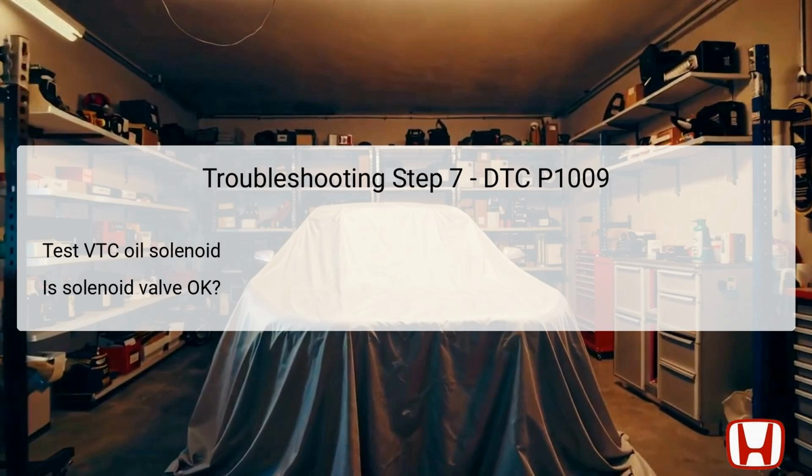Documenting the results of this test is crucial as it directs the next steps in the troubleshooting protocol and ensures that subsequent components are not unnecessarily replaced. Following the verification of the VTC oil control solenoid valve, the next step involves inspecting the VTC actuator itself. The actuator is responsible for receiving oil pressure from the solenoid and adjusting camshaft timing. If this component is damaged or malfunctioning, it can cause significant timing discrepancies, leading to the re-emergence of DTC P1009.